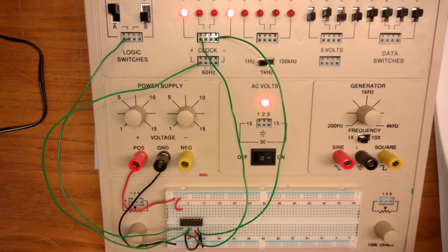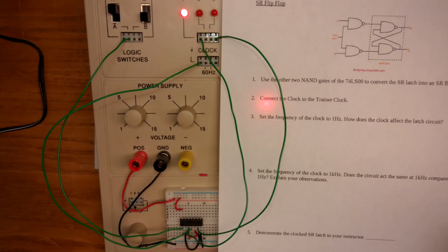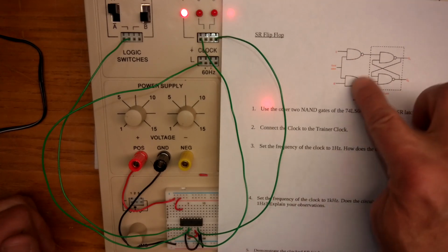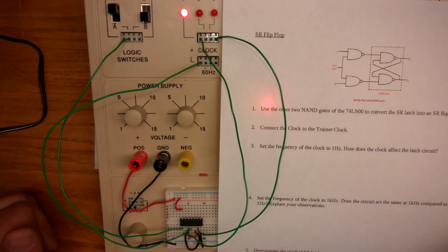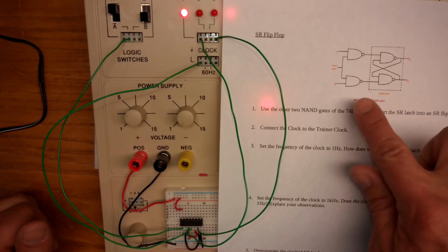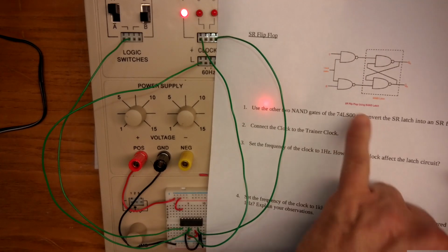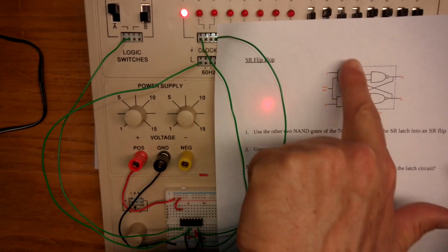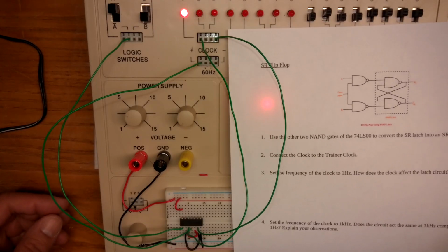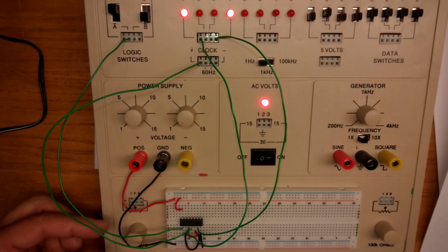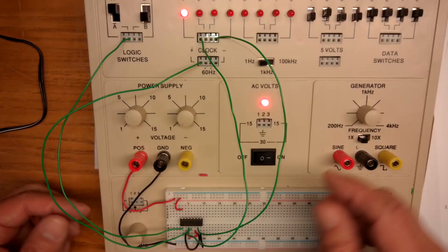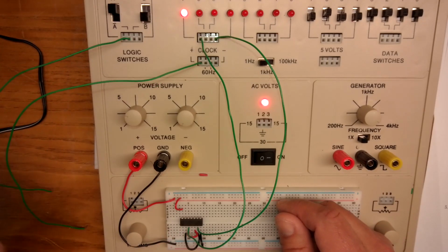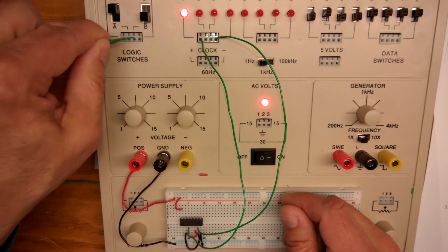Okay, when I'm done with that, what I want to do next is we're going to use all 4 gates to build an actual SR flip-flop. So I'm going to use the 2 other NAND gates as inputs to my current existing circuit. So this one with the hashes around here, we already built. That's what's going on the bottom. All I need to do is my inputs now need to come from the other 2 NAND gates. So I'll take them from the far side of my circuit. So I'm going to remove these for now. We'll come back and add them in a second, but this will be SR.